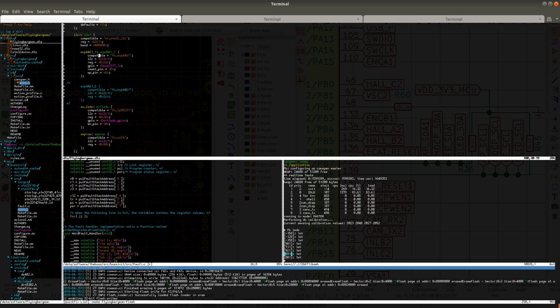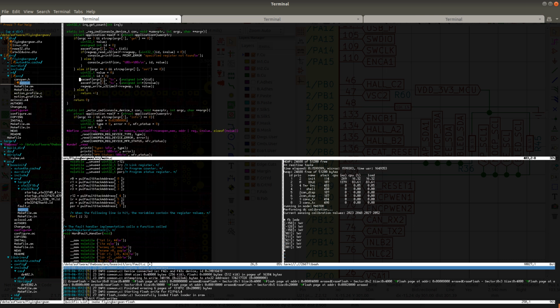I've had some problems with the I2C. But what I'll also do is actually refactor this driver to use interrupts. It's going to take a bit of work to get that done, but when that is done, then the driver is actually not going to be blocking, and it's going to be possible to get proper timeouts, so that things don't just freeze. Let's see. I'm just going to fix this printout.